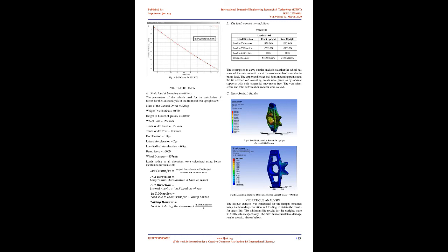6. Material selection. The material selected for the component is aluminum alloy 7075 T6, as it has a high strength-to-weight ratio and better fatigue properties than the other lightweight aluminum alloys such as 6061 T6. The properties used for the analysis were as follows.